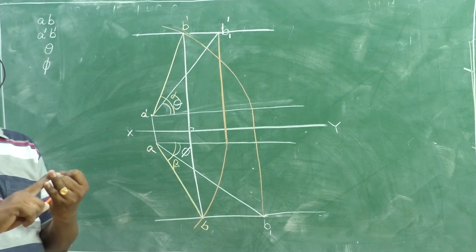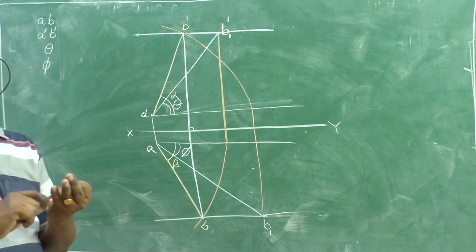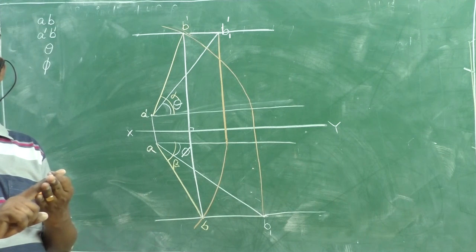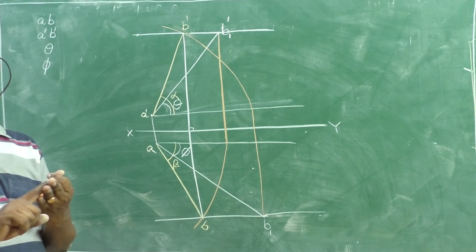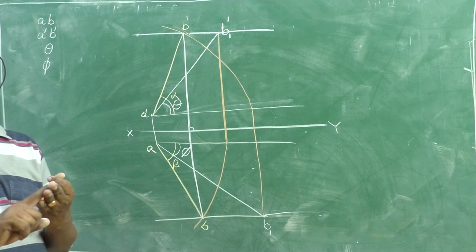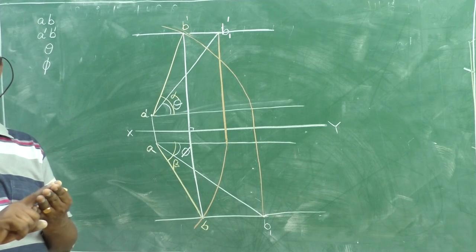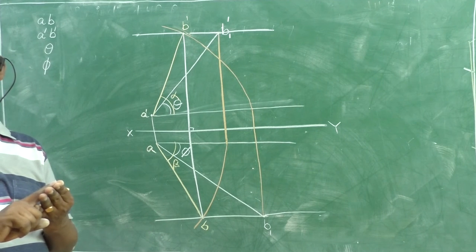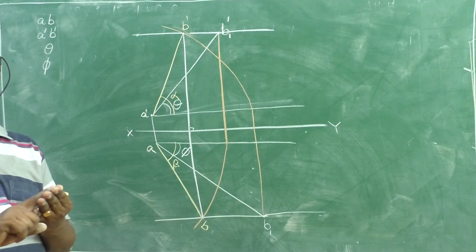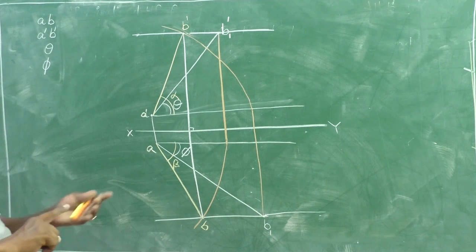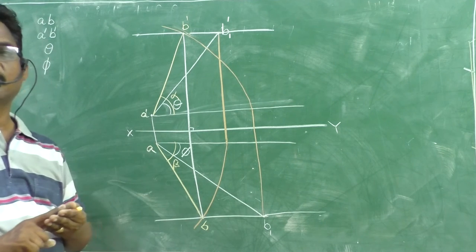view and top view. Third point, you need to draw the locus line through the moving point in the front view and top view. That locus line is a perfectly horizontal line, or parallel to the reference line. Now, fourth point is project the moving point in the front view downwards up to a horizontal line which is passing through the fixed point in the top view. After that, with the fixed point as center, you need to rotate it. That will cut the locus line in the top view, and if you draw a line to that cutting point, that is the required top view.